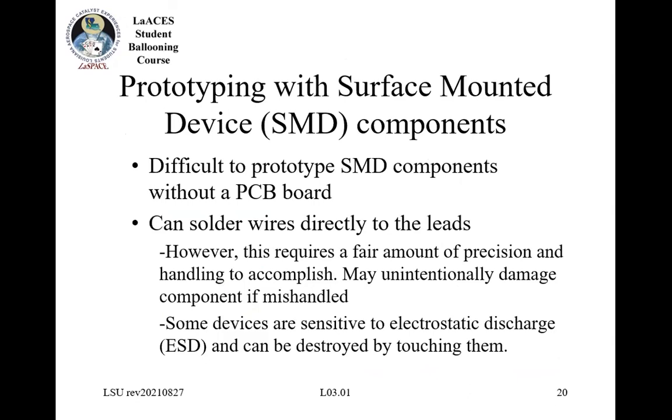Then you need to make sure that you select a through hole part rather than a surface mount part, because we're going to be working with the through hole part today, so you'll see it, but the surface mount component will not fit in the same board as a through hole. So very different. It's important to know what you're ordering whenever you're ordering components, and we'll learn more about this next semester.